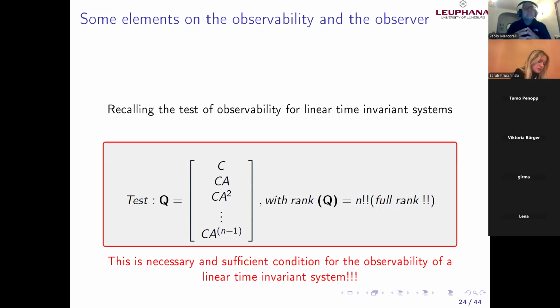The system, God knows about the system. We have just a representation of the system. In fact, we have matrices C and A. To be precise, the model of the system is observable. This means if the rank of this, I will do it with MATLAB together, is n, it is sufficient to say that the model of the real system is observable.